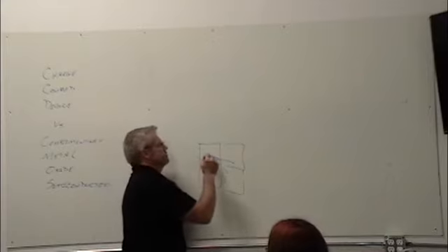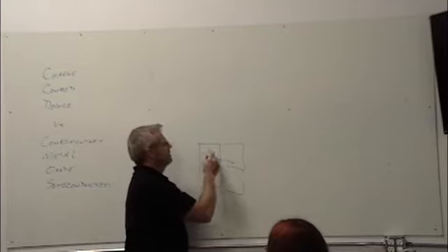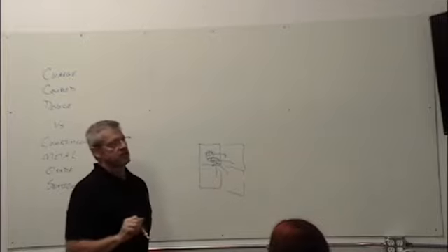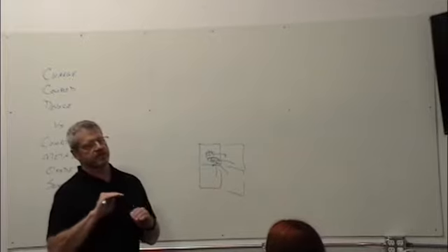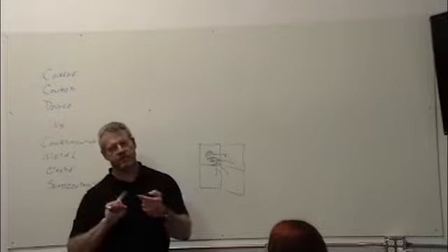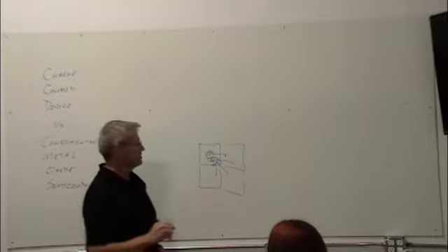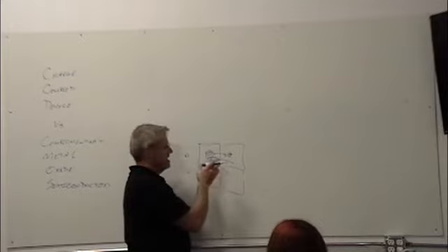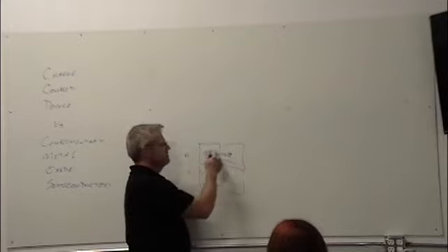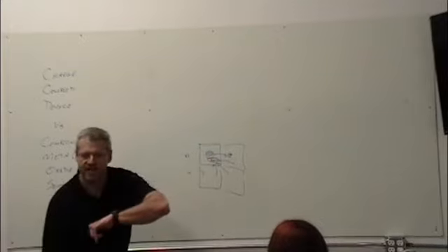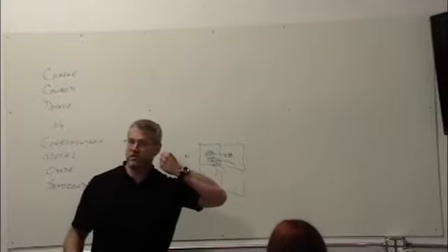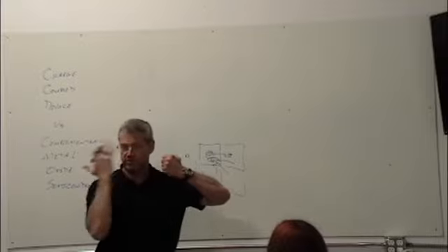You can play games where if you've got a bright pixel, you basically adjust the gain on the pixel based on a weighted average of all of its neighbors. So if you've got relatively dark pixels, they'll have high gain, but the bright one, they'll invert and push it down. So, if you take a picture with your camera of me sitting here with a light bulb, you're just going to get a light bulb and not much of me, right?